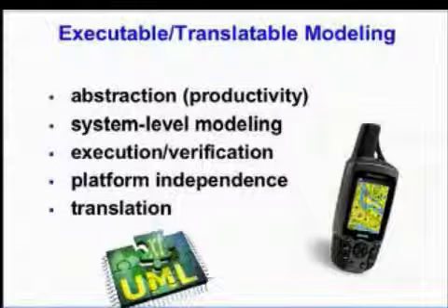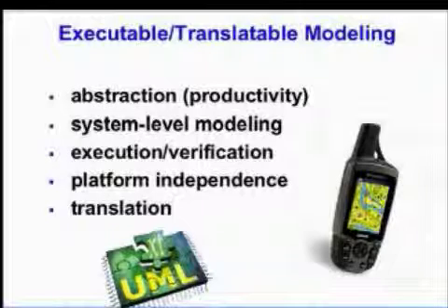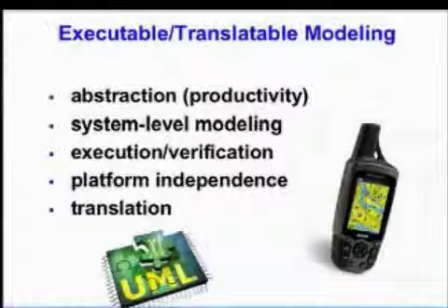BridgePoint performs executable UML, so we can begin executing and therefore testing and verifying our application right from the first day that we begin modeling. The models that we will build are platform independent. What that means is that I can change the target and maintain the integrity of my model because I have built a model that is not dependent on details of the target. And translation allows us to take that platform independent model and generate code for platform specific targets.